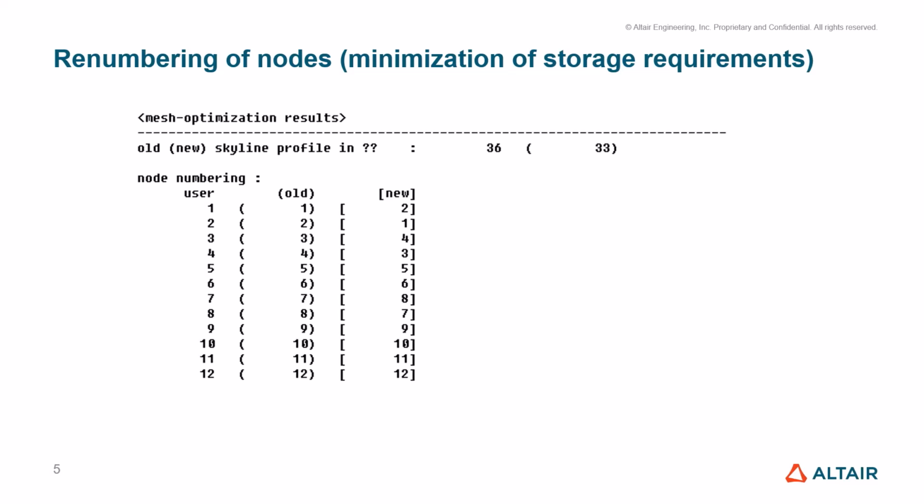Finite element analysis and structural analysis software like S-Frame internally renumber joints. That is necessary because the user could choose any name for a joint. So when you build this structure, you don't have to start from joint number 1 and go to joint number 12. You could say for the first floor, I'm going to use numbers like 100 and 101. For the second floor, 200 and 202, or 5 or whatever. So the program has to renumber them internally in order for them to be consecutive numbers.